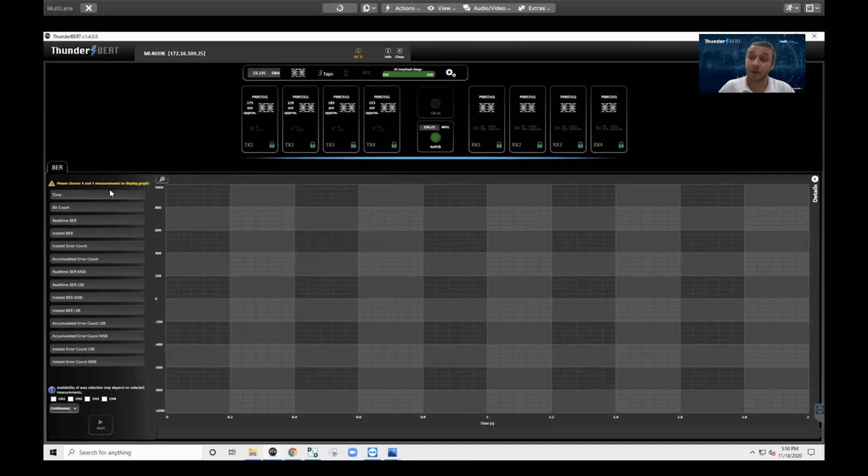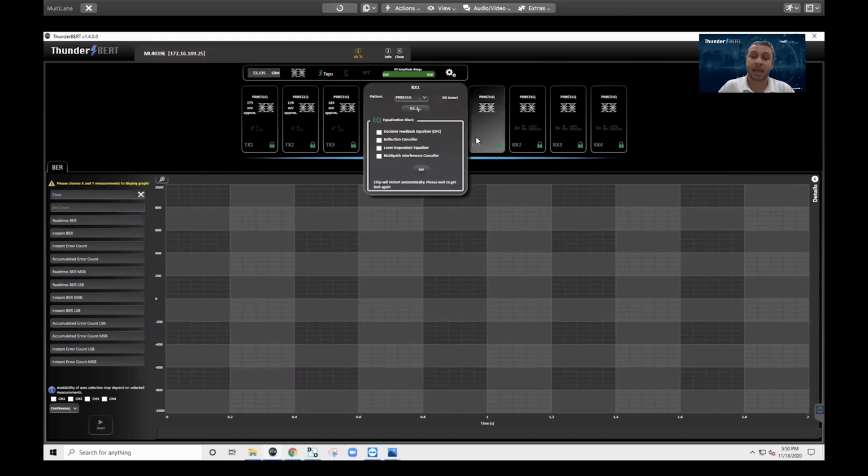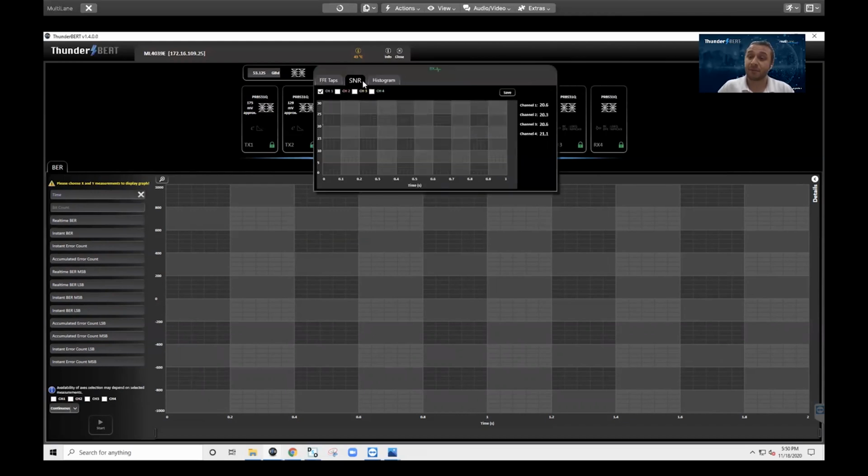So now that we have some errors coming in, let's run that test once more. And something I'll show you is that now that we have degraded those output signals a bit, I can select all 4 of the SNR metrics to show that we're running now at 20 dB instead of the 25 dB which we were running with the optimized signal.